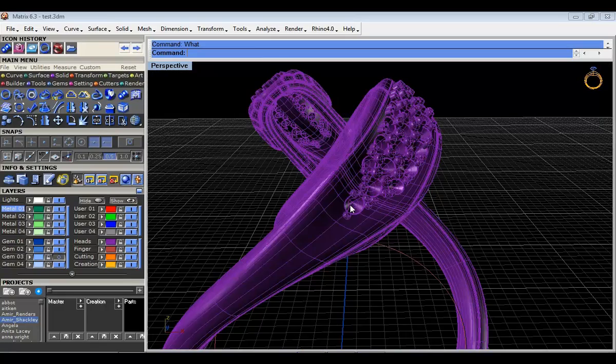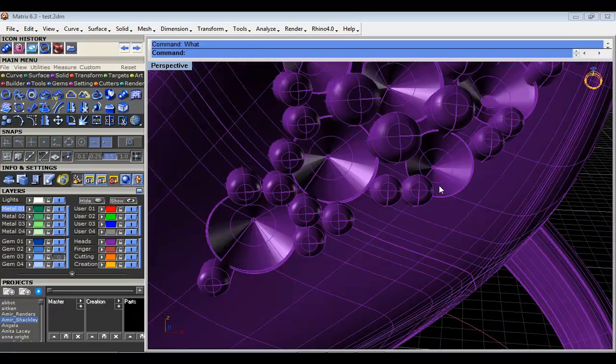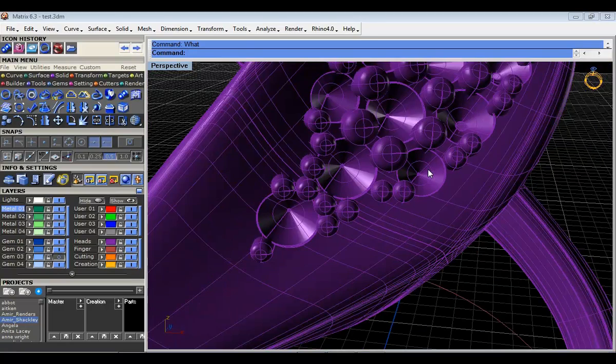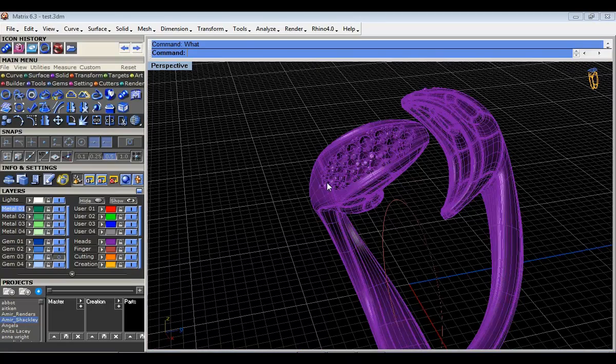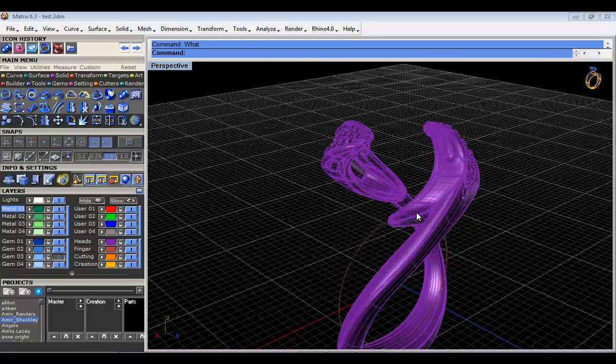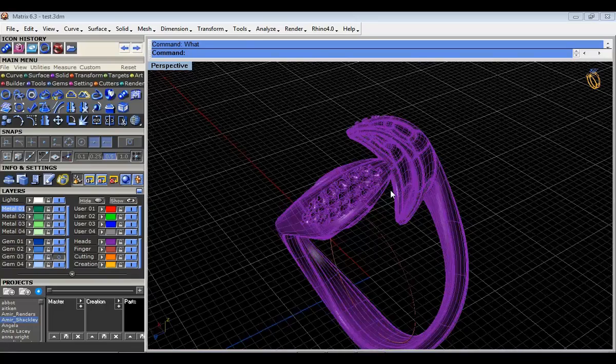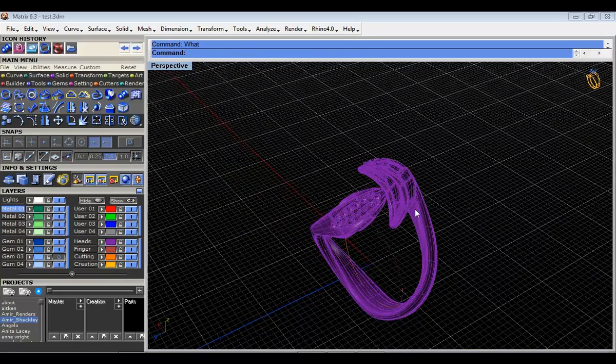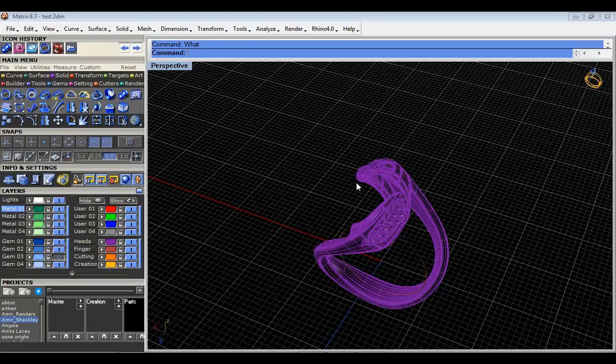Good points. Most of the guys out there that have been doing this for a long time know that if you've got to mill this, your cutter is not going to get inside that gap, so this is going to become blended. If you're going to grow this, half of this detail is going to be lost when you polish it away. So in my scenario, it's less of an issue than possibly in other industries, say auto mechanics or something where a small drawing is turning into a big thing, like let's say the side of a car panel. Yep. For those guys, I think it would be a lot more important than it is in the case of a jeweler. Yeah, I think those are excellent points.